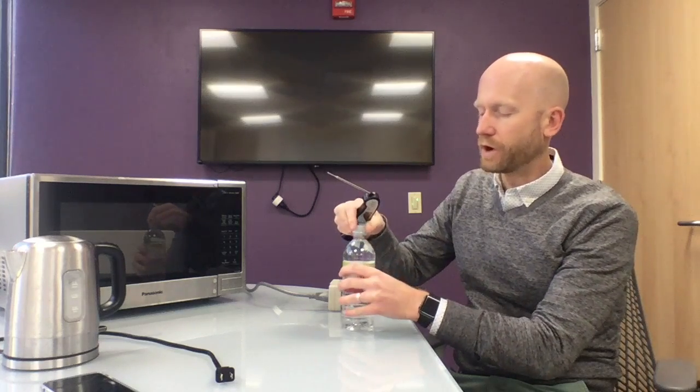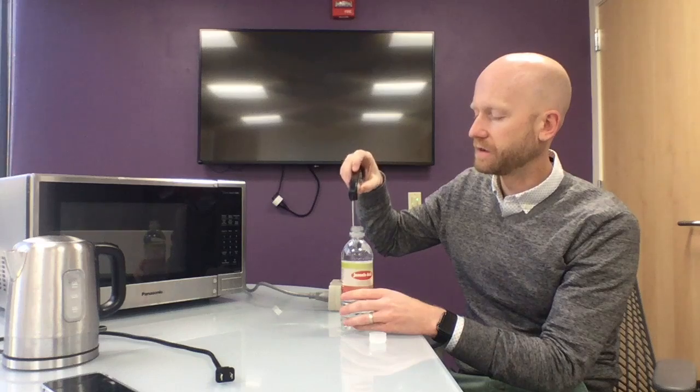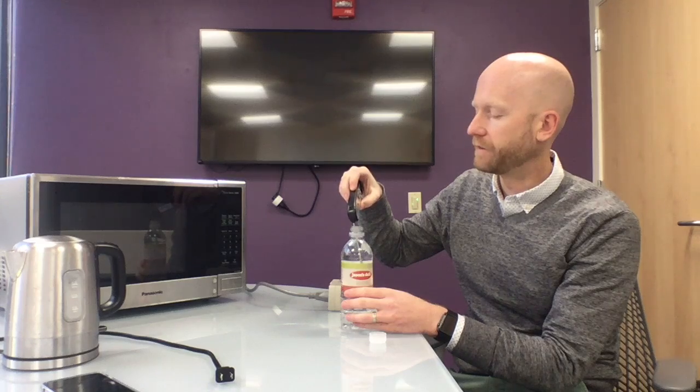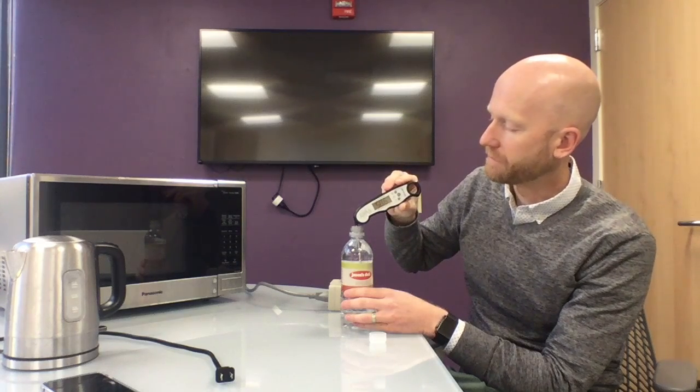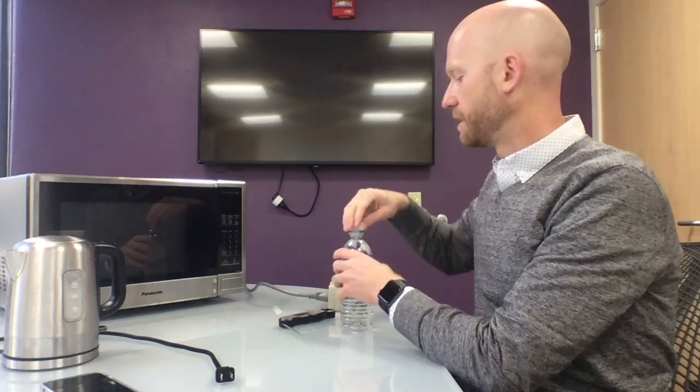The first step is to put in the spreadsheet the amount of water that I'm using. As I mentioned, it's 500 milliliters, and since we know the density of water, we can calculate the mass of the water in this bottle. I would want to note that in my spreadsheet. The next step is to measure the temperature of the water. I just got it out of the faucet. I emptied the bottle because it was pretty cold, and then filled it with more water. I can see from this thermometer that it's about 58.5 degrees. I'm going to note that in my spreadsheet.